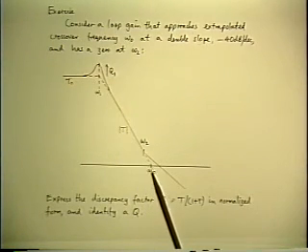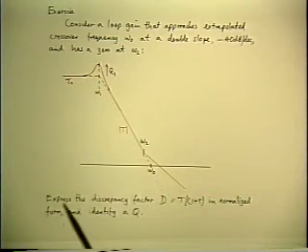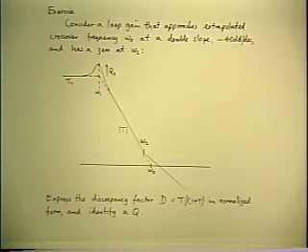Write the factored pole zero form for T, plug it into the expression for D, which is T over 1 plus T, and see what happens to D. See what its shape is. See if it has a quadratic. If so, what is it that determines its Q? So it's a parallel problem to the one we've just done. Look at that for a few minutes, mainly just to the point of setting up the problem, which is writing the expression for the factored pole zero form for T.